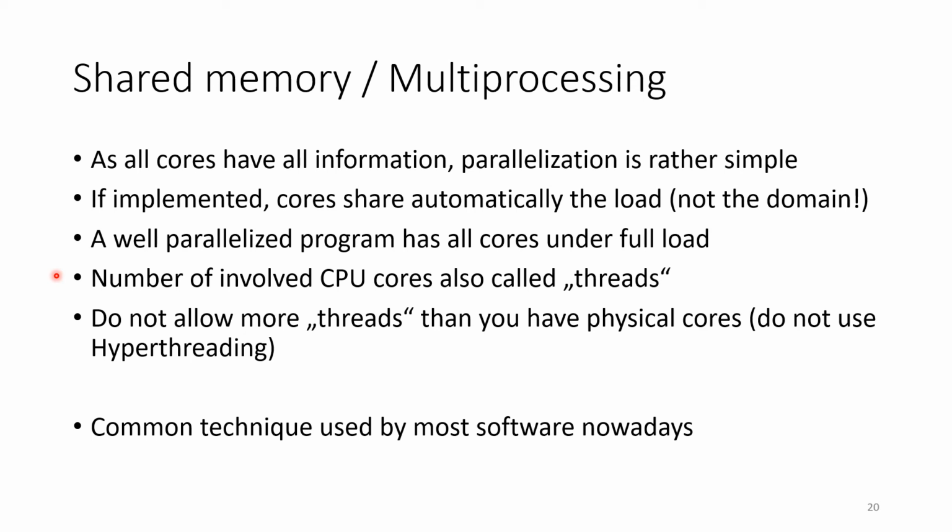So it gives you what can be done in parallel. But for example, if you know, well, I'm running the simulation on this computer, but on the other side, I also have to do, I don't know, check my emails, write a report, whatever. So you might want to say, okay, I will use 3 cores for your numerical simulation. You will have 1 core spared for whatever else to do. Then you have 4 cores, but you would just open up 3 threads for your simulation.